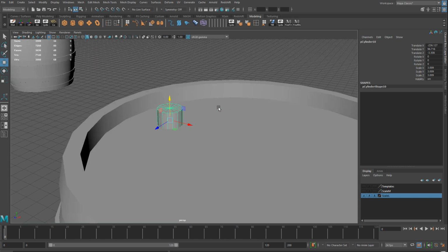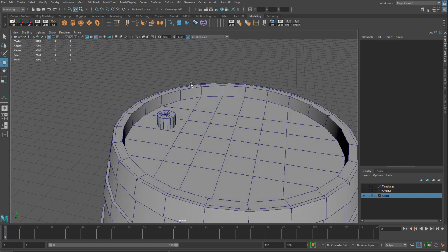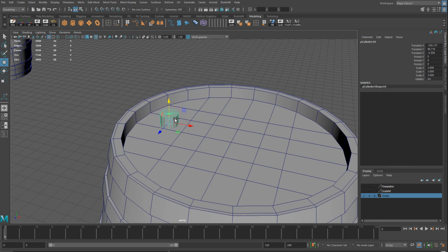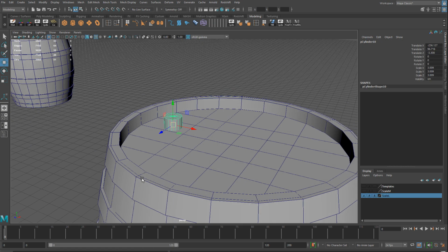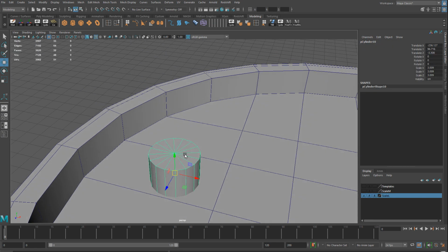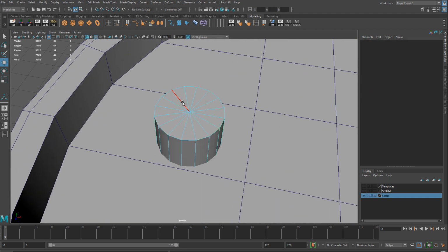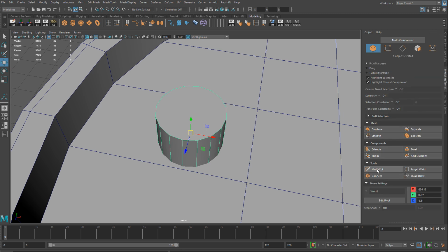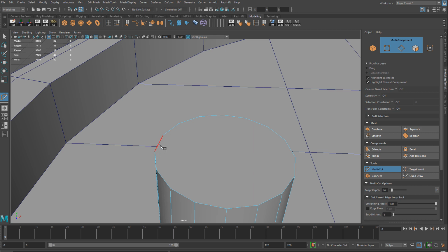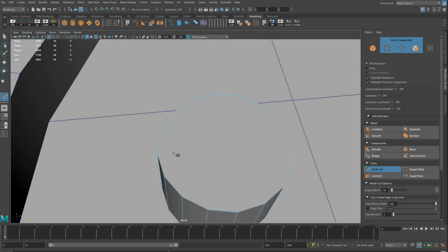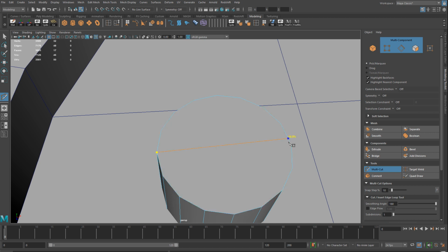So for the top one, to keep it low poly, I would keep it just as is. First I'm going to go ahead and delete the bottom faces. I will never see them. Let me select them, hit delete, and Control 1 again to bring everything back. And I would probably just fix that pole again. So let me do that really quick. Control delete, and I'm just going to use my multi-cut and reconnect everything like I did for the other part. Oh, let me undo just in case I didn't cut across somewhere by accident.